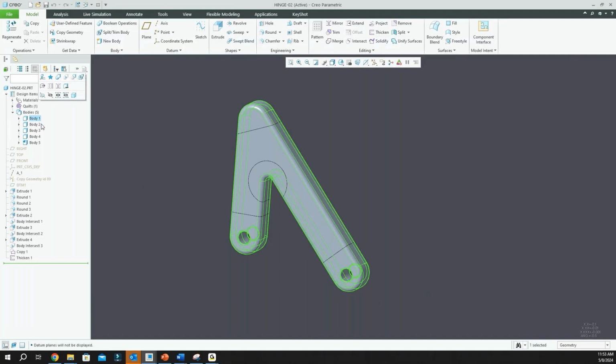So this is the geometry to start with. Take it away and optimize this geometry and recreate the geometry from this in a way that will reduce the mass. And then I also have body 2, 3, and 4, and all those bodies are bodies that I'm telling the optimization study to preserve.